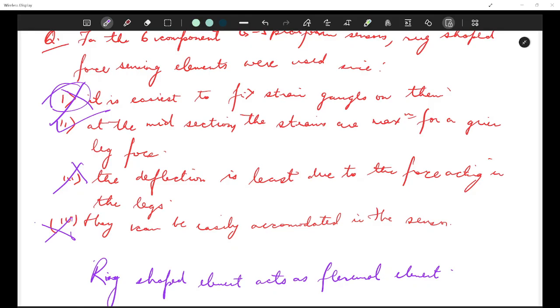So a traditional 6-6 Gough-Stewart platform: it cannot be singular in all 6 directions at the same time, it can be statically isotropic, it cannot have dynamic isotropy, or it can be dynamically isotropic. Okay. So the first statement is it cannot be singular in all 6 directions at the same time.